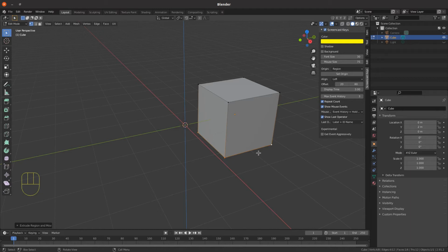And with using vertices, that is the general principle of how you build models, is by extruding items out. So we'll now look at edges, and as we said, we've got the vertex, edge and face select mode. So if we go on to the edge select mode, or you could have pressed Shift number 2 or Shift number 1 for vertices to toggle on and off those modes.